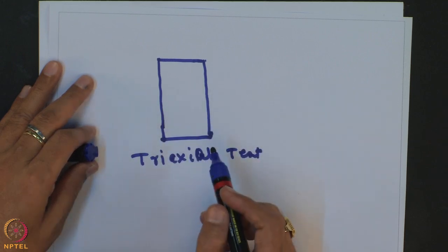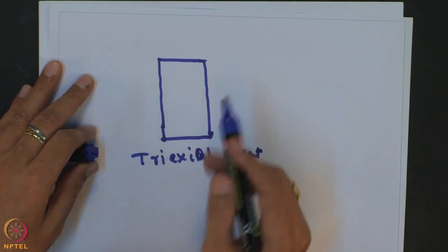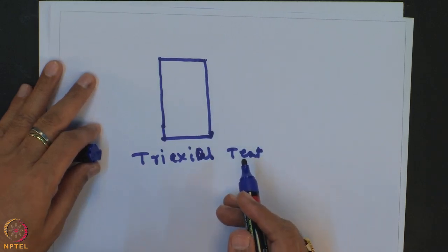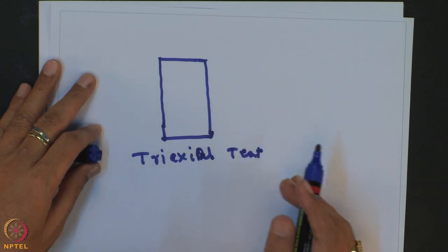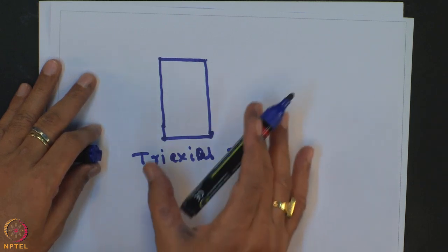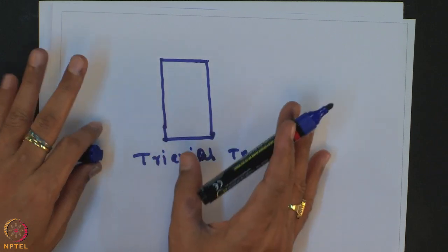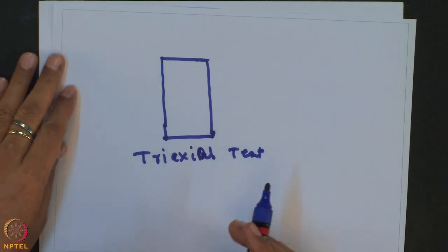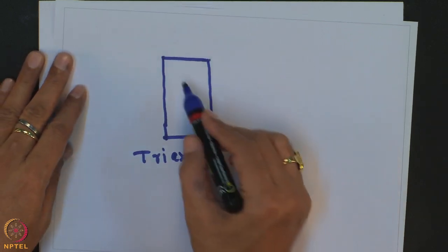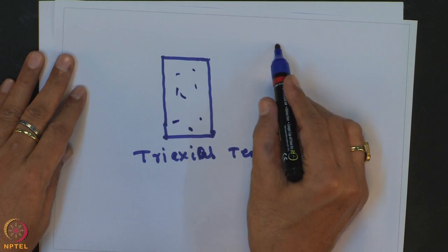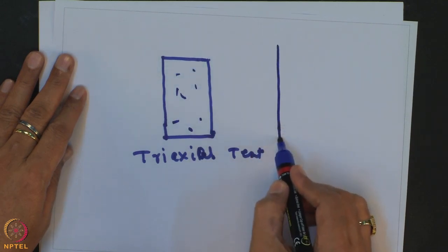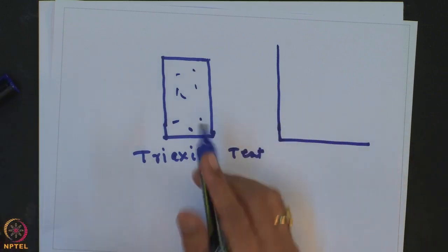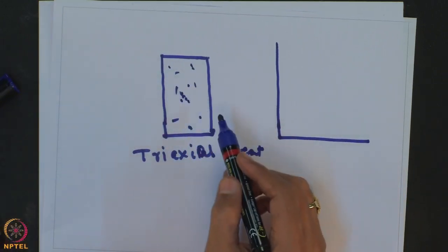From this test, let us say for a particular confining pressure of 21 kilopascal, you can represent the baseline shear strength data of the sand itself. So, you can draw the curve for the dense soil sample. Let us say that this is the unreinforced case, when geotextile material is not there in the sample.